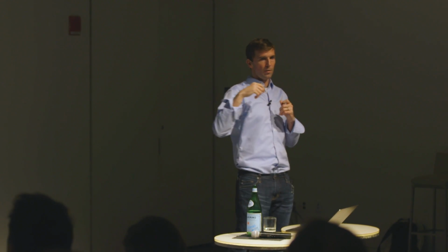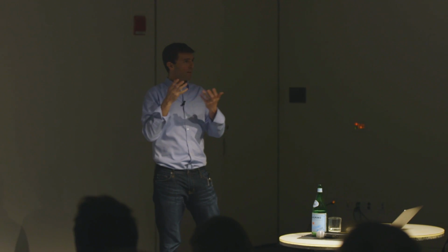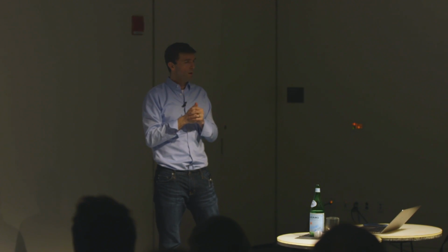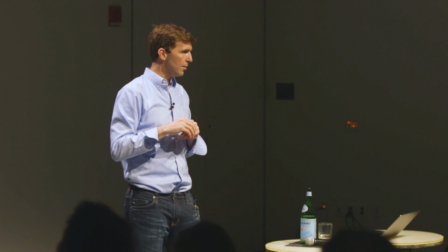It turns out that the silicone-based elastomers that we use are porous to water, and the pluronic that's used as the ink will break down into water and then self-evacuate. So you have voids that are formed more or less for free at the end of this process. That's the vasculature, the main internal structure of this device, and they also figured out ways to print platinum-laden inks as well to do the catalyst site.